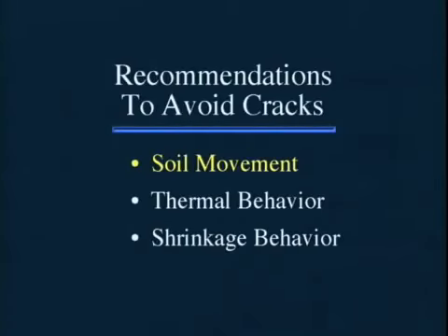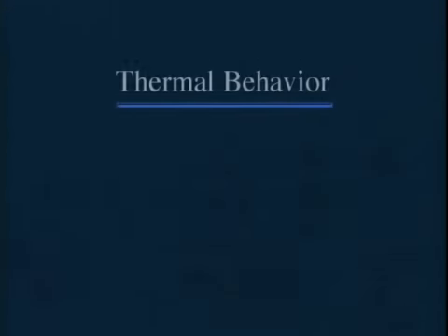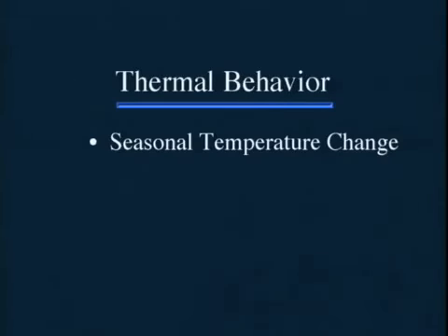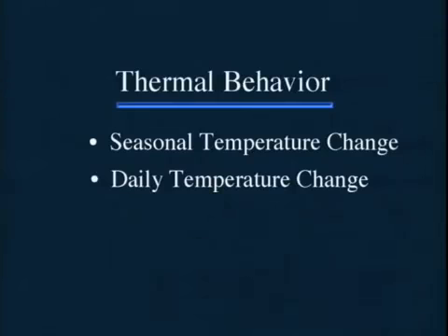That covers soil movement. Let's move on to thermal behavior. These topics follow those covered in tape number 1. Under thermal behavior of concrete, there are 3 main causes of cracking. I'll cover recommendations to prevent cracking due to seasonal temperature change, daily temperature change, and heat of hydration.